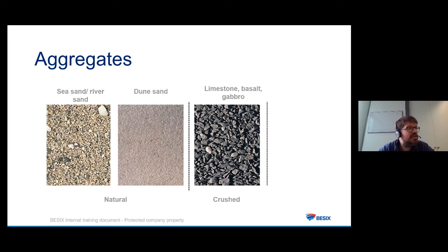The magic number, actually, that's really practical. I don't think that there is something like this in a book. It's just by seeing it. If you have something around 300 kgs of round sand in your mix design, you will be able to pump it. That's, of course, really general, but just start with that, make some tests, and you will see if you have to increase it or not.